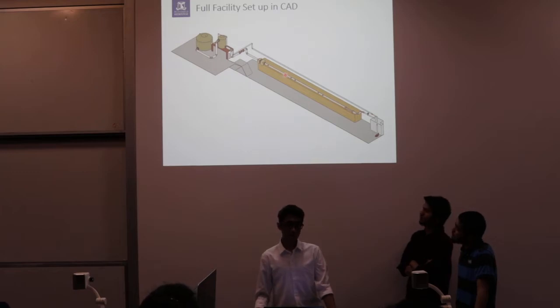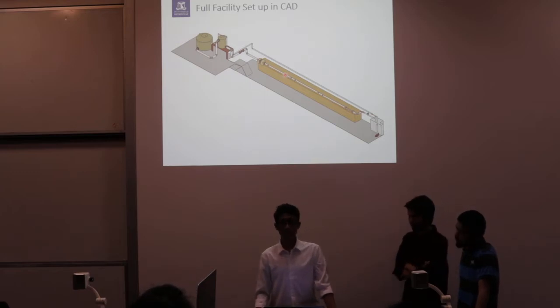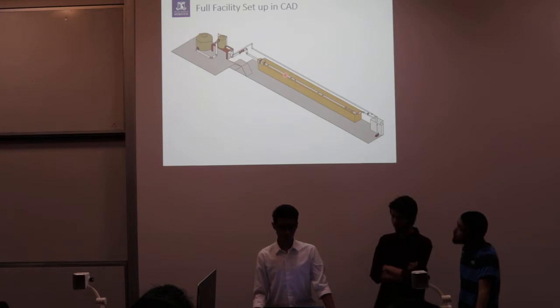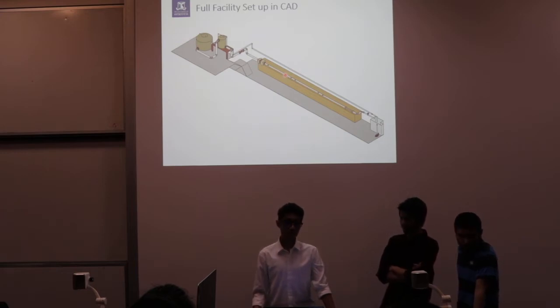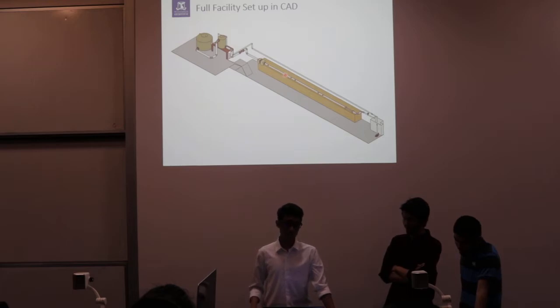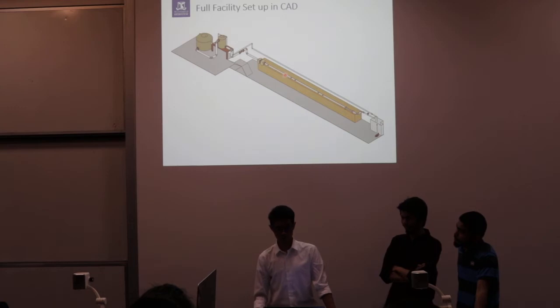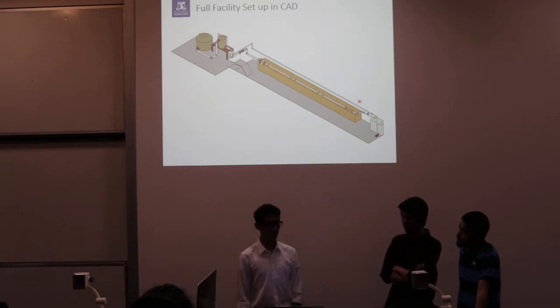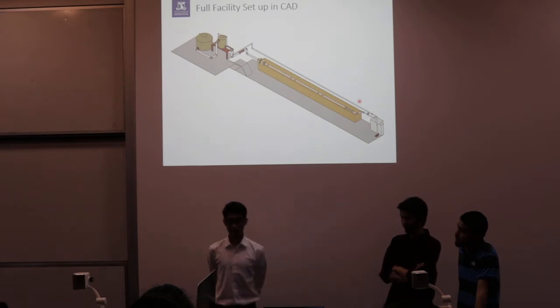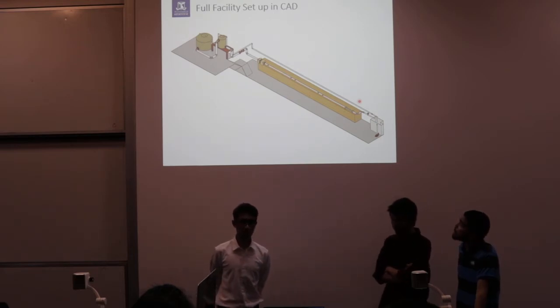So that's going to be the pressure measurement system. We're using just one differential pressure sensor, and we have to design a way to use that one sensor to measure the pressure difference across 10 different pressure taps. That will be our next design objective for the pressure measurement system.